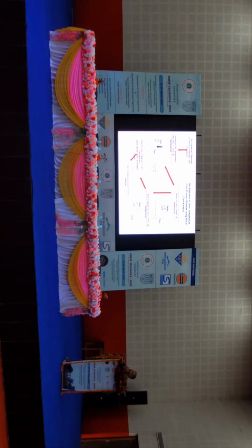Oh, sorry. So after getting the degree of cure, what do you have to do? You have to differentiate again at every point. In the degree of cure versus time plot, you take the slope at each point, and you will get the rate of degree of cure. So you have a lot of classical cure kinetics modeling. For example, nth order kinetics, you have already been introduced to nth order kinetics, right?